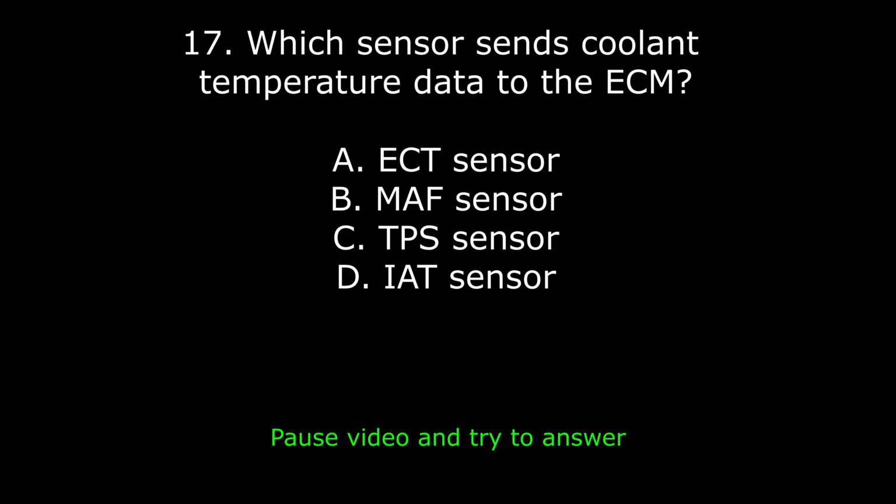19. What should be checked after replacing a hood that contains an anti-theft latch switch? A. Door alignment. B. Switch function and wiring. C. Hood insulation. D. Radiator pressure. Answer: B. Switch function and wiring. Improper latch switch wiring can cause false alarms or inoperative security system.